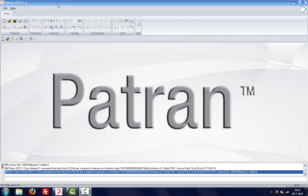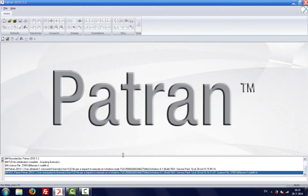So once you open PATRAN, when you launch it, this is what you see. Of course you have a license file which is coming from some kind of FlexLM server. Mine is coming from the TU Delft FlexLM server. This is my computer that is connected and authorized to get this kind of license. Now what you see here is that the window is divided into a few parts. On top you will have the toolbar. Once you have a new model open, a lot more things will show up. Here there are shortcuts for many operations that you can carry out for pre-processing and making all kinds of options to set up the processing step.